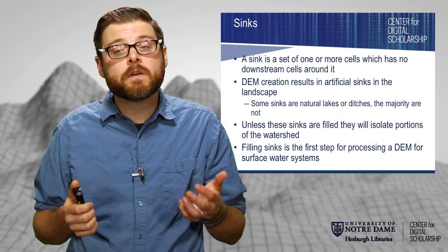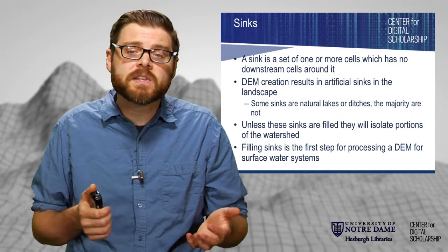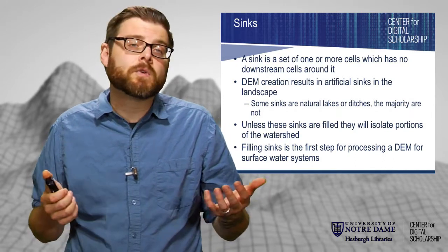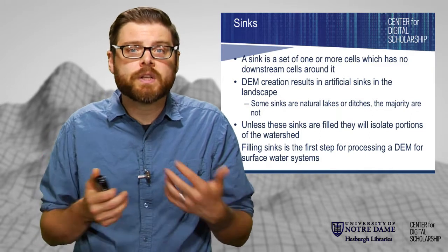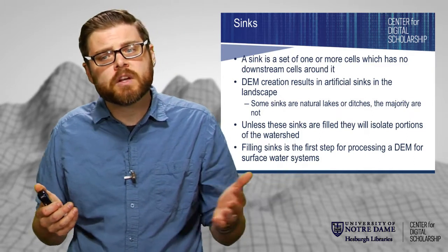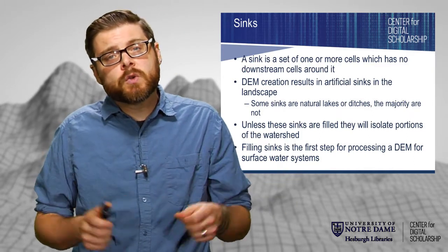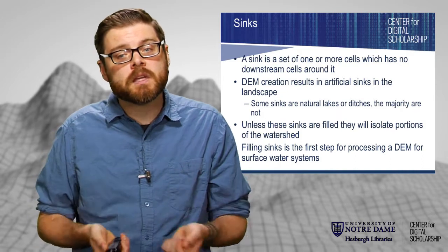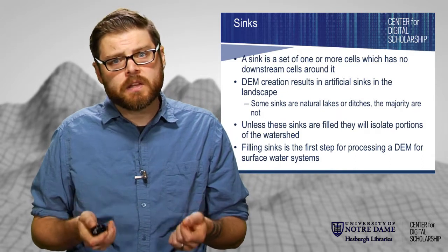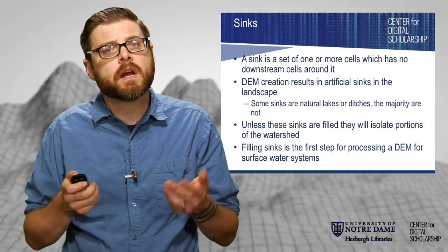So unless these are filled in or processed in some way, it's going to isolate portions of the watershed and make it so you can't really analyze how water is likely to flow across the entirety of it. So usually filling sinks is an early stage in processing a DEM for use in hydrology.